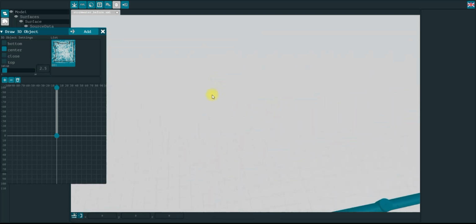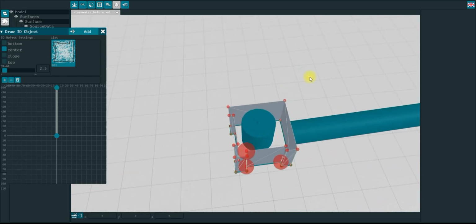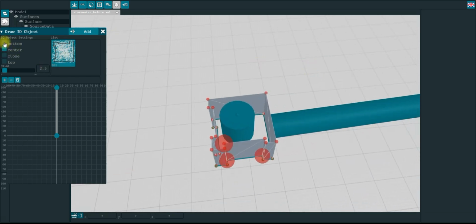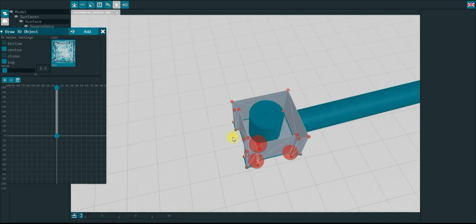So then you see there's basically a cube, but it has no top and has no bottom. So there are bottom and top functions here. If you choose bottom, it's gonna cover this side. Basically, bottom refers to the part of the model that's not attached to the line. I probably should change those names. Anyway, if you press top, it's gonna create triangles that are encircled by the initial line.